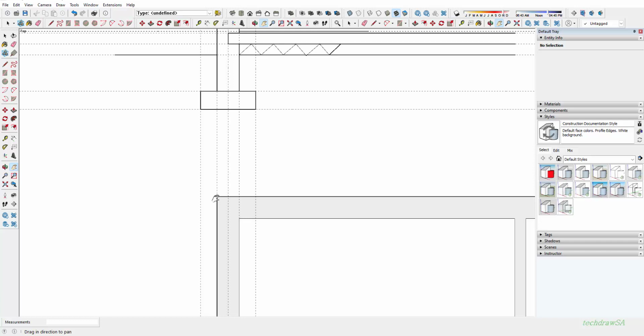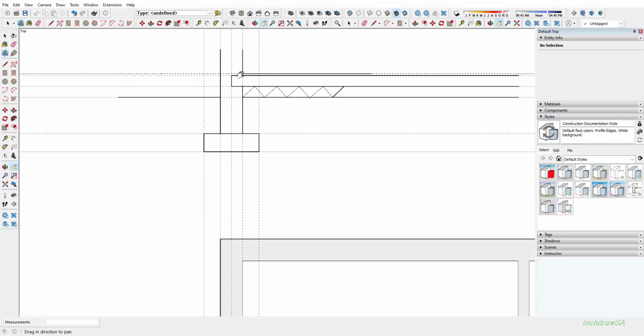So these projections that come from the floor plan, look closely on these constructions here. You can see that this external line on the external wall represents this line on the far left, and then the inside of that external wall's line is projected up here. You don't start your foundation on that corner. The foundation is still dug out more to the left and to the right, and obviously at the appropriate depth.